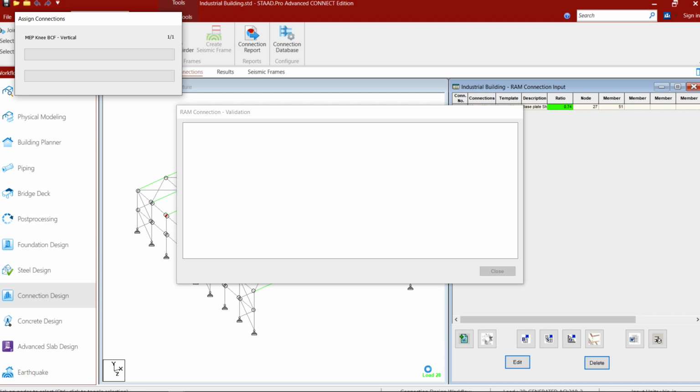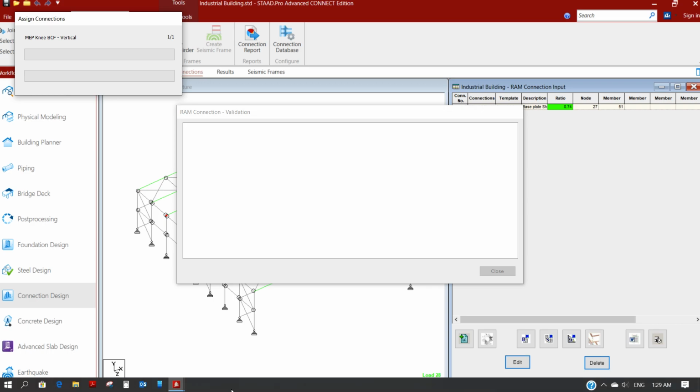If you remember, we considered the seismic loading conditions. We considered the wind load also. So because of that, whenever a seismic load is considered, the knee connections like that have to be designed as per AISC Guide 4 or Guide 16. There are two guides which are used to design such type of connections, and of course STAAD uses those provisions. For the time being, I can show you those two. Let me see.